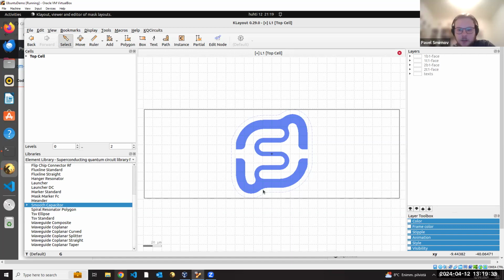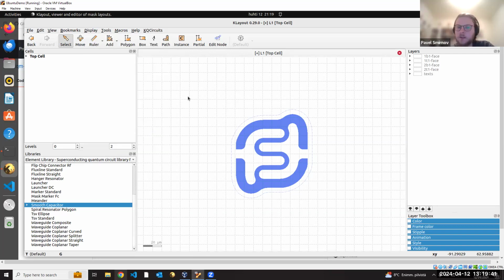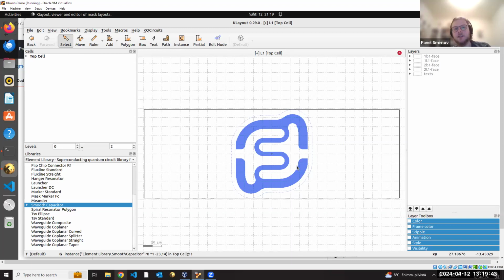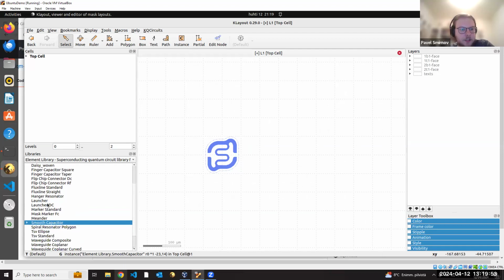So to show the full hierarchy you have to press the asterisk button, and actually in here, display full hierarchy. This is the same equivalent command. So whenever you think that you can't see stuff, just make sure to press asterisk, and usually that solves the problem.